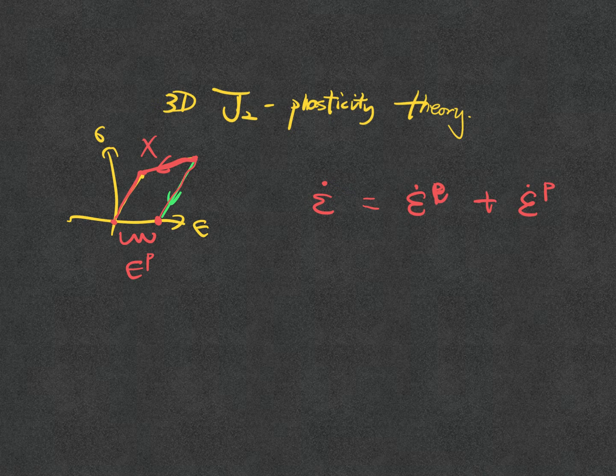Okay, so this is the theory of elastoplasticity. In plasticity theory, we assume that if there's a total strain, meaning that there's a change in the length or the shape of the material, it is either elastic or plastic, but not anything else. Okay, does that make sense? So you can have multiple scenarios. If the material is elastic, then elasticity implies that the total strain change is equal to the elastic strain change, right?